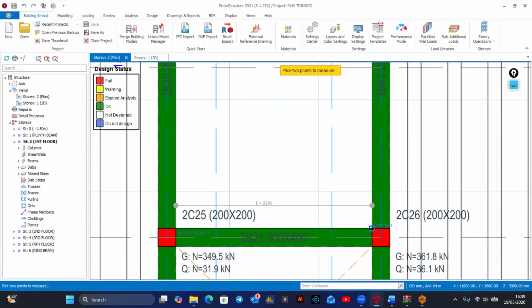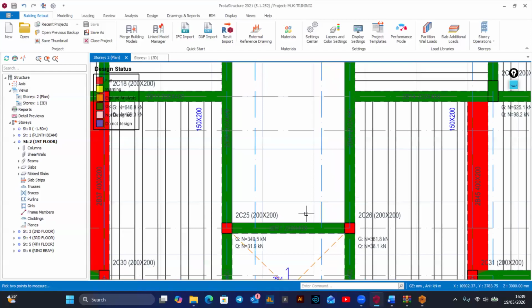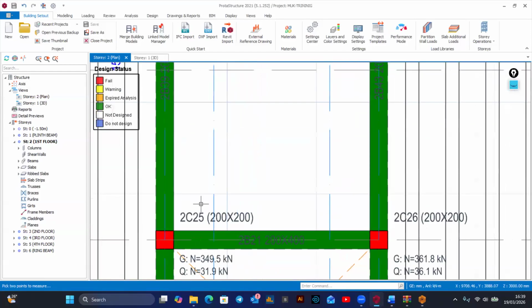The recommended, yes, that big gap is called the stairwell. Because now the recommended flight width is 1.2 meters, and our total space that we have, including the stairwell, is 2.2.